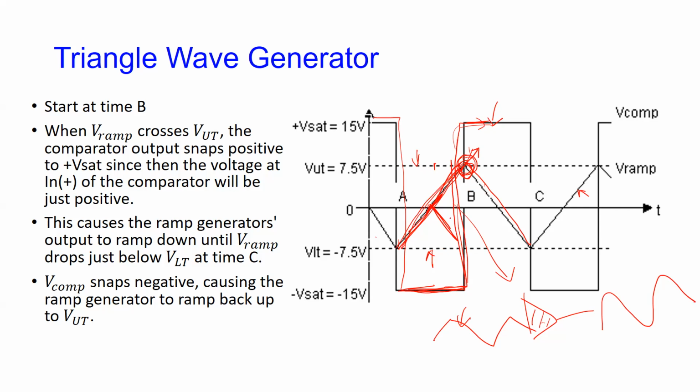This is fed back, so this is a positive going step. The integrator produces an integral of a positive going step, but inverts it. So you get a negative ramp being created here, until it reaches a negative threshold value on the comparator.